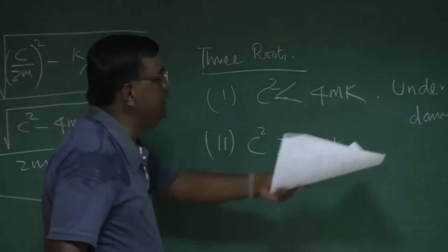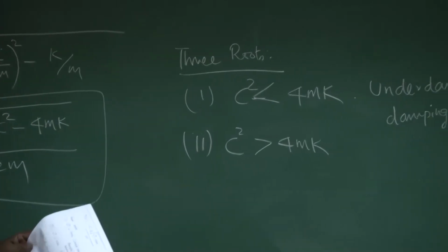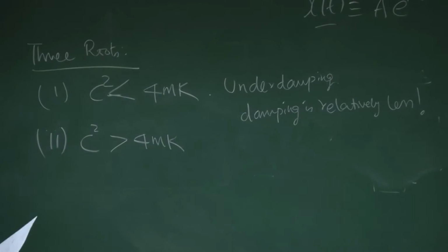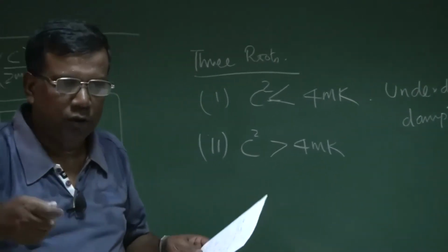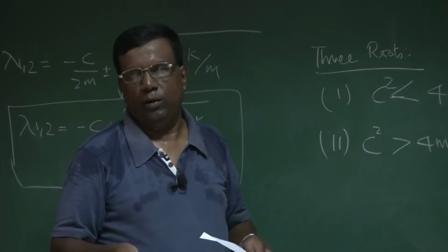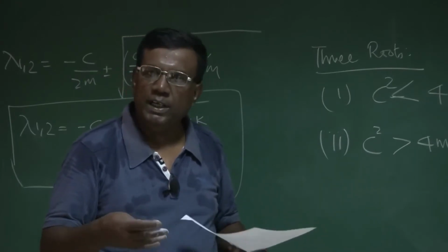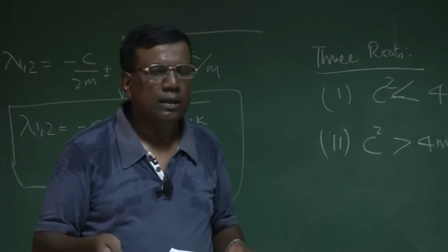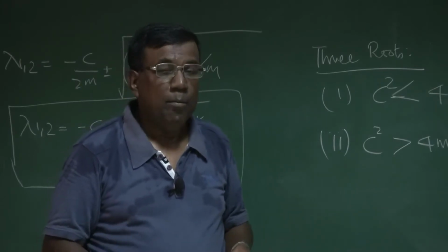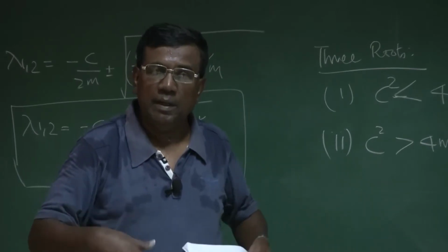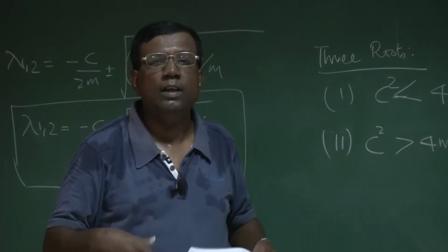The same understanding here. Now we know damping must be pretty large. Okay? Think of a situation. Suppose we take a mass spring shocker system, right? Mass spring, and there is air around that. So that there will be friction, and some energy will be lost through air friction. It will have some damping. But if I replace the air by water or oil, the damping will become large, or c value will increase.